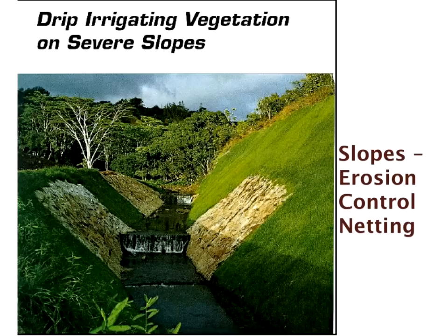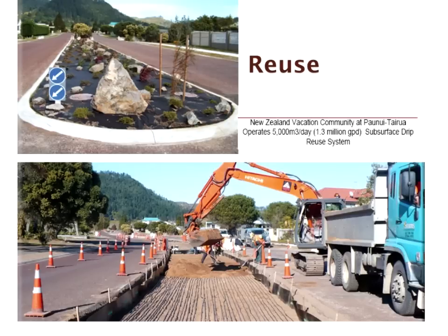And of course, there is erosion control netting. They put down erosion control netting. The contractors had to rappel on ropes down the hill in order to put the drip lines in across. But they did it, and there are beautiful results. This is in Hawaii. And there's no reason that you can't put in a drip system on a slope, but as I said, you have to be careful. They put the drip line in and then tied it to the erosion control netting. So technically, there's no reason. You just have to take precautions.